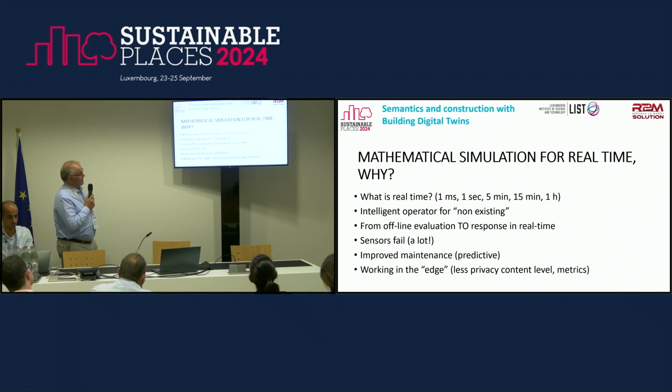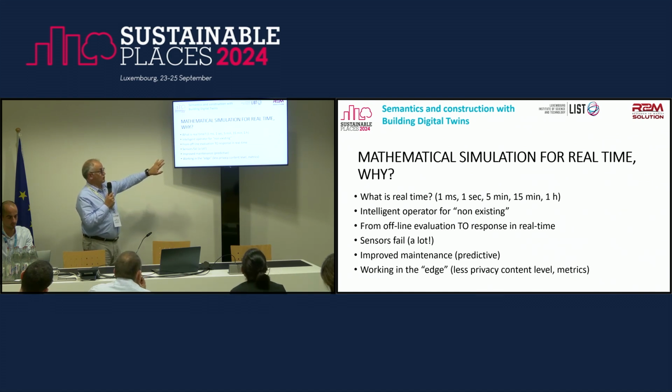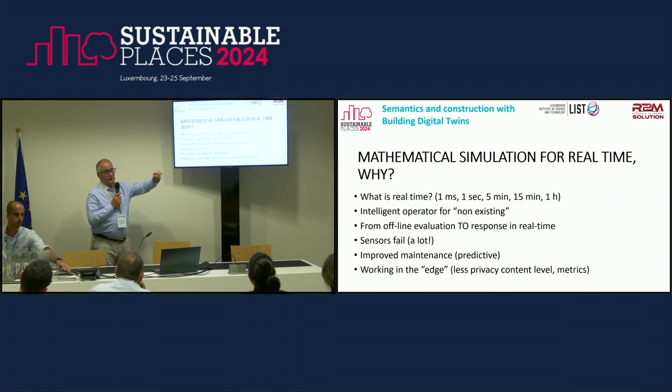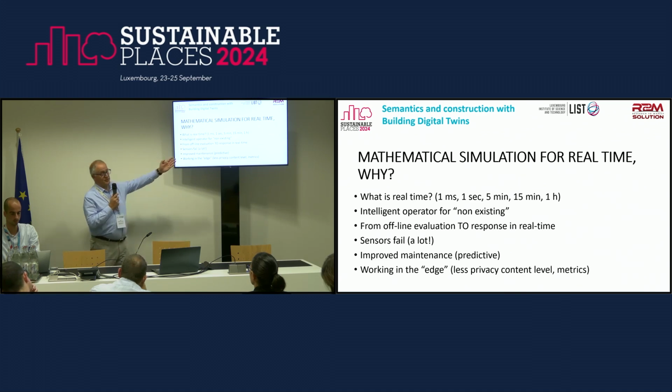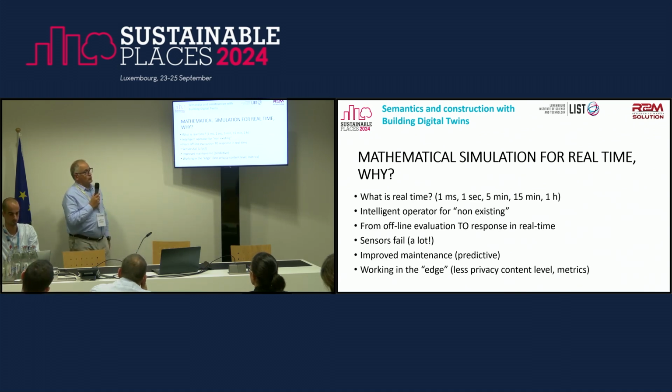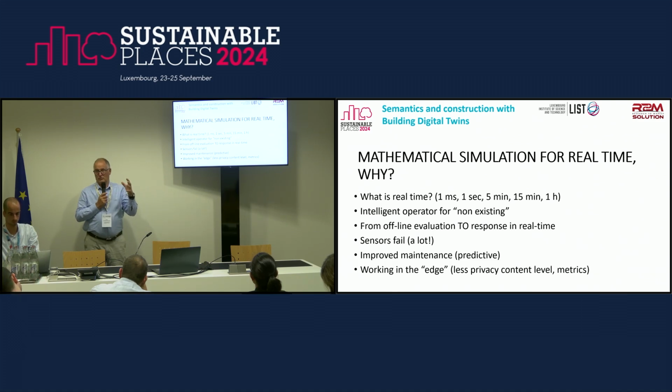When we speak about real time, we can have processes of milliseconds, seconds, 5 minutes, 15 minutes, 1 hour. If you are collecting information on the energy performance of a house during 1 year, obviously the sampling is going to be 1 hour. If we want to work in real time with buildings, perhaps 1 millisecond means enormous historical files, so it's non-practical as well.